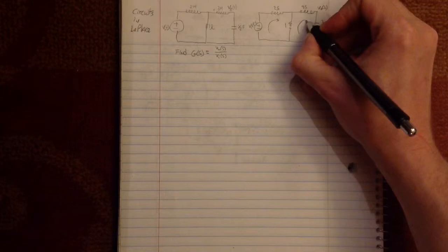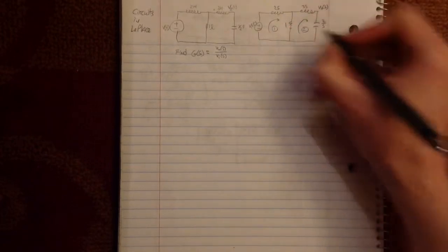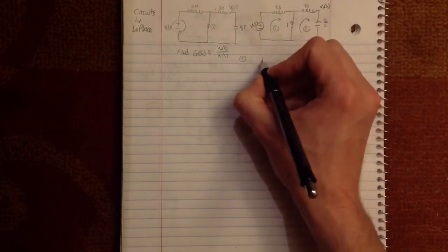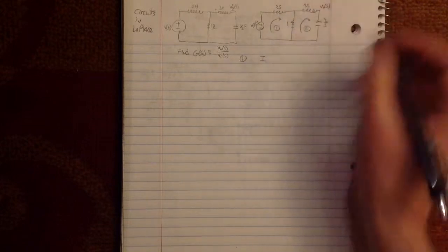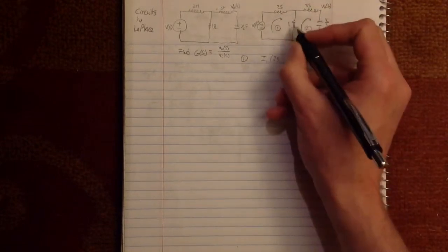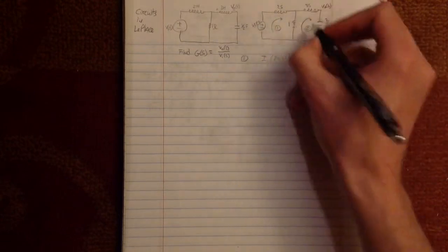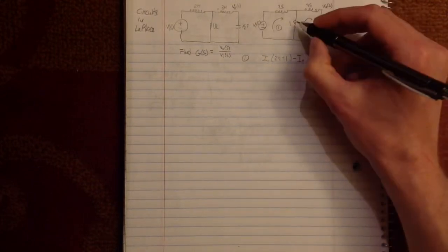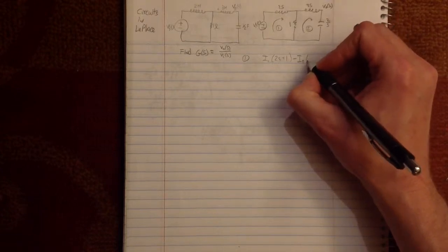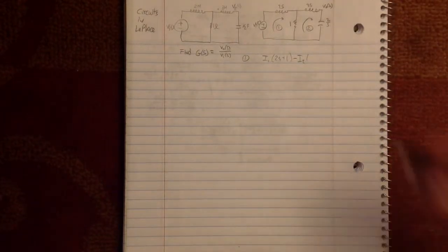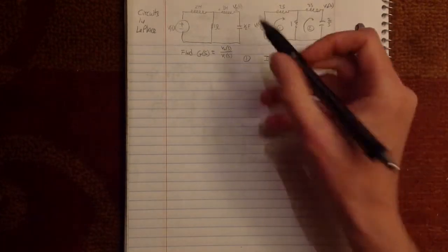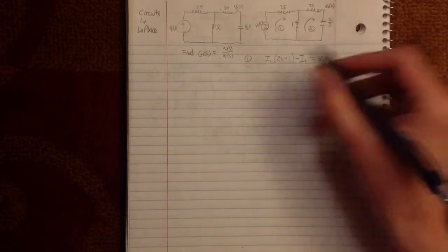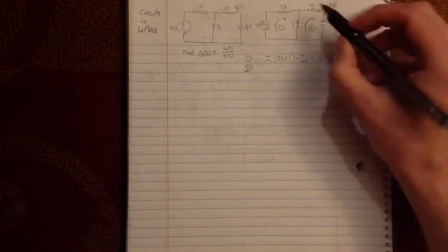Okay, so we're going to use mesh analysis, call this 1, call this 2, and let's get the equation for loop 1. So I1 is going to be 2s plus 1. That's it. But we've got the current coming this way from 2, so write minus, because it's the opposite direction, 1, so just I2. And then minus Vi of s equals 0, or you could just simply write equals Vi of s. Simple enough.